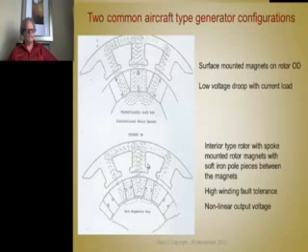The designs are very carefully initiated, such that at a certain sustainable short circuit current, it won't cause this thing to burn or cause a fire and cause a plane to crash and the pilot get killed. That's carefully designed so that the voltage drop from the flux linkage drops as a function of a certain current that allows the short circuit current to be sustainable. And so this is really a field weakening that takes place. It's a high fault tolerant machine. This was developed by GE, by a research group up in Schenectady. To this day, aircraft generators are made this way.